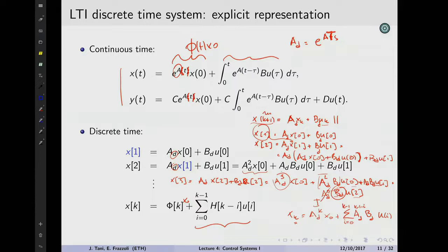first of all, the class stuff that you studied works in continuous time. The big deal here is that there is nothing defined between two consecutive instants. The representation doesn't exist. In the world of natural numbers, there's no rational number, right? So you cannot do Laplace transformations in discrete time. But there is an equivalent transformation, called the Z transform. And we will hint to it here. We will do it later on.